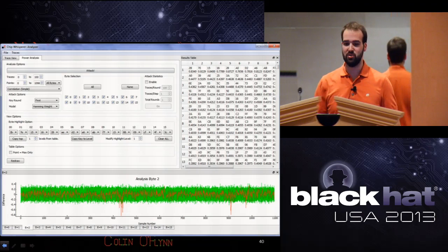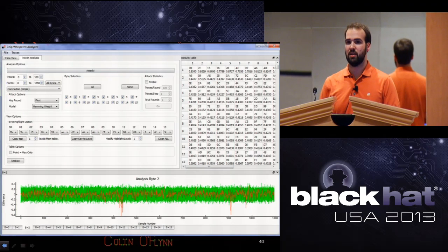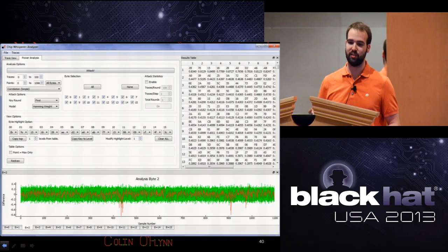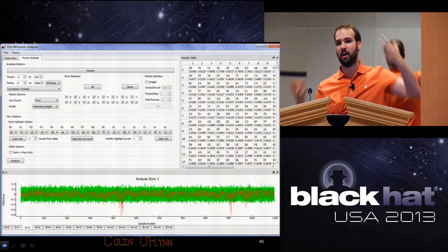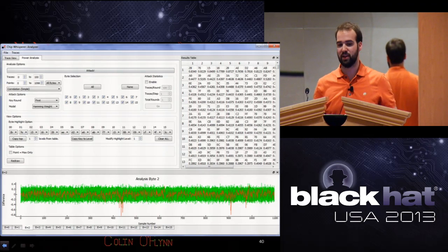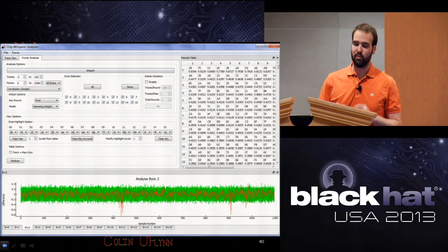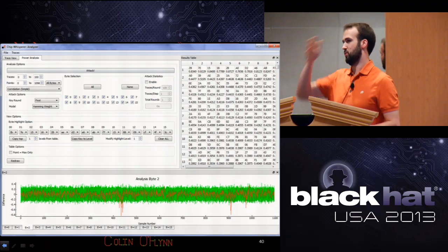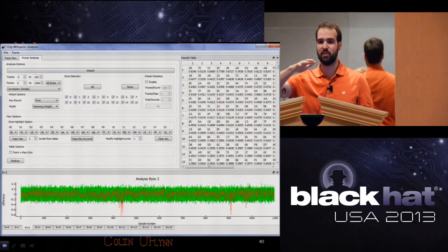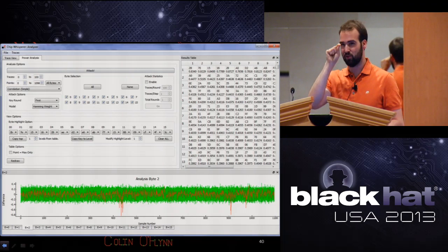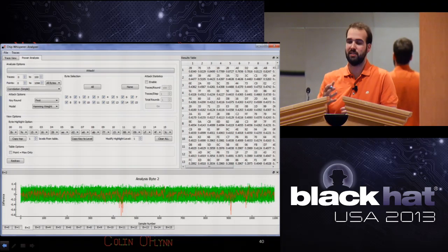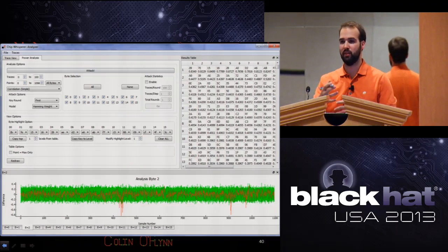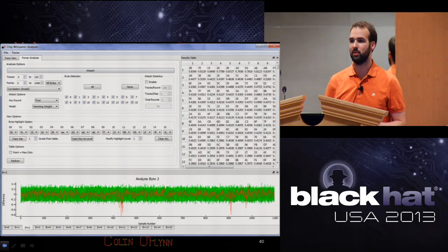But if they don't, you can also do some trace resynchronization, because in real systems you'll have interrupts and stuff that are screwing you up. Very briefly, you do some sort of autocorrelation. You correlate one power trace with the next one, and you say at this point the rest of it is lining up. The convenient thing is that there are only very small variations. For example, the encryption will do a bunch of subroutine calls that are all the same, and then a bunch of stuff that's all the same. At some point the data differs, so the power is a tiny bit different. So you will still get really good correlation between the two traces because they're mostly the same, and then they line up as usual.